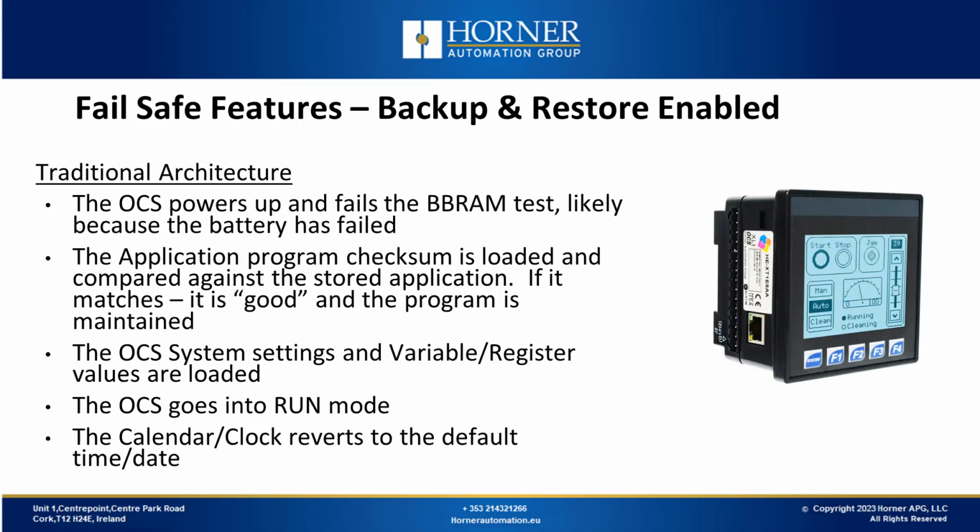In the case of traditional architecture, if you encounter a battery issue and have used backup and restore, it can prevent your program from being erased and preserves a functional set of register values. This allows you to continue running your system until you can replace the battery and restore your calendar clock. This is especially critical for traditional controllers since a battery failure can result in the loss of your program if you haven't utilized this feature.